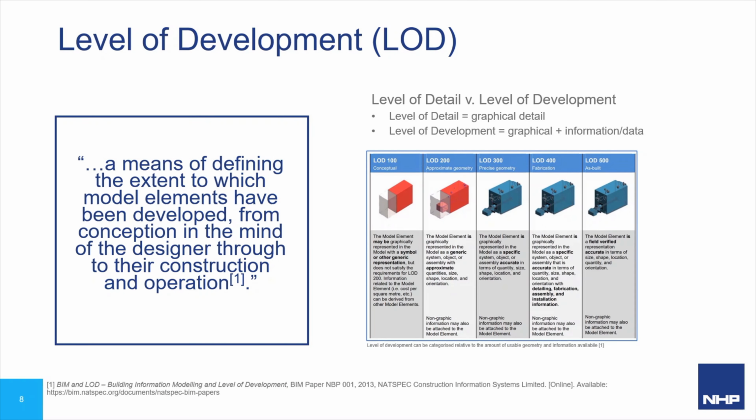With all this talk of BIM file formats, this is as good a time as any to touch on the level of development, also known as LOD. LOD can be described as a means of defining the extent to which model elements have been developed, from conception in the mind of the designer through to their construction and operation. The acronym LOD is used for both level of development and level of detail, both terms relevant in BIM. While similar in concepts, level of detail can be considered the level of graphical or geometric detail in a model, where level of development describes the overall state of a BIM object.